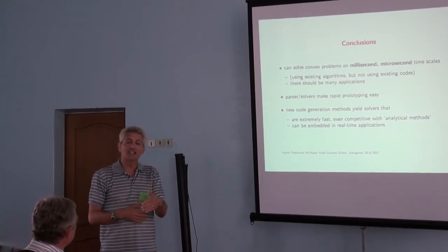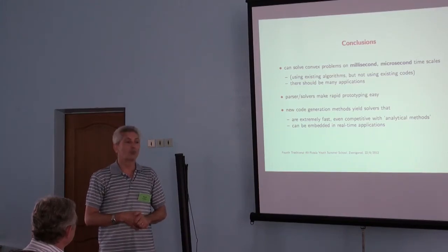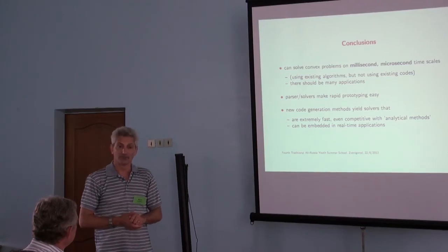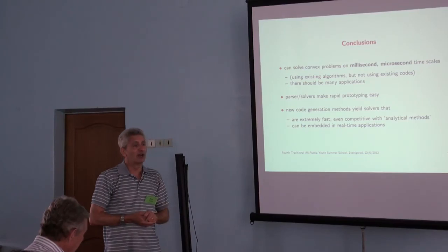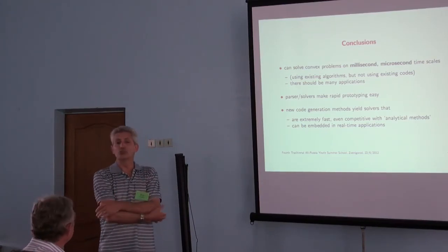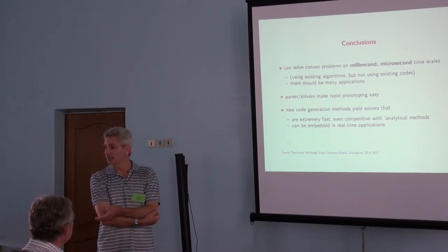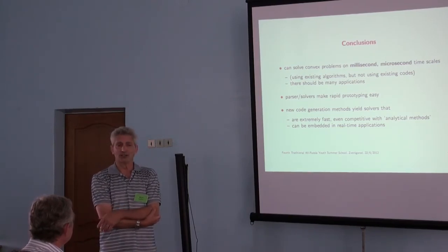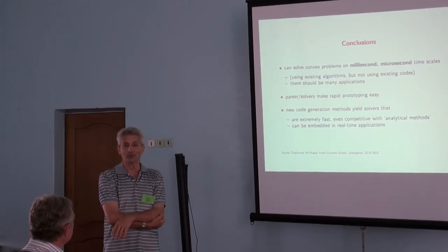We find that things like 10 steps and 20 steps are more than enough for any application. There's no application where that's not enough. And in fact, we even do things like, for fun, we run MPC where we do 2 steps. And you haven't even achieved feasibility. So this would be completely insane to do. And guess what? You get excellent control. I'm not recommending this, but anyway, that's it.